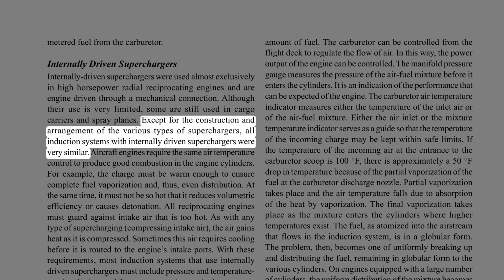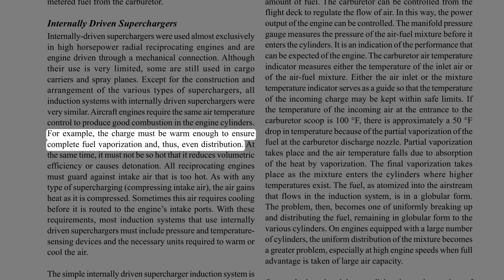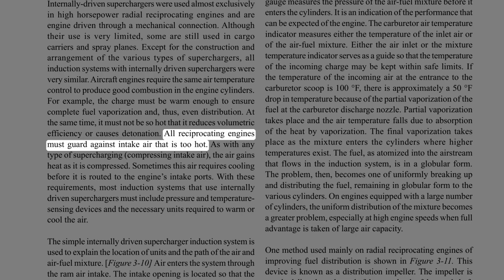Aircraft engines require the same air temperature control to produce good combustion in the engine cylinders. For example, the charge must be warm enough to ensure complete fuel vaporization and, thus, even distribution. At the same time, it must not be so hot that it reduces volumetric efficiency or causes detonation. All reciprocating engines must guard against intake air that is too hot.